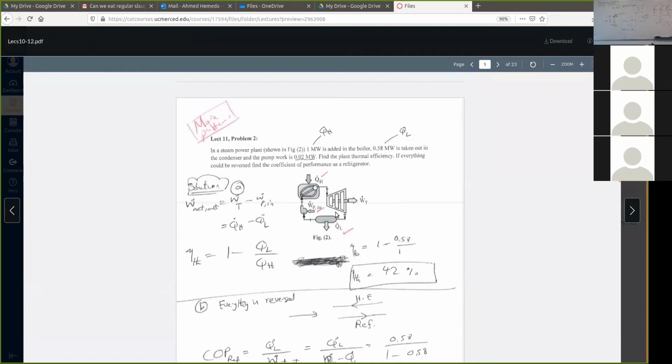Usually we draw high temperature on the top and low temperature on the bottom. If it goes from high temperature to low, high energy to low energy, like a turbine, the input is at the top, not the bottom. The compressor is the opposite, from the bottom to the top, because energy increases. So we have a turbine here. That's the way we typically draw components of an engine.